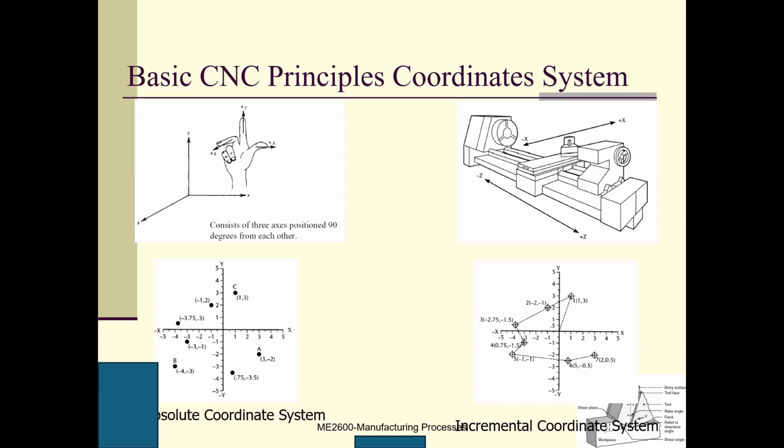When you program and you write for each slide, for each command, you write, I want to move this position, I want to move that position, and then the system can precisely follow your instruction to move the tools from one position to another. So here is called absolute coordinates. Some very highly sophisticated systems have the relative coordinate system.